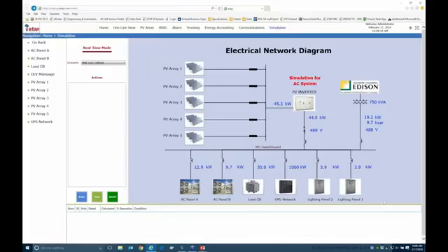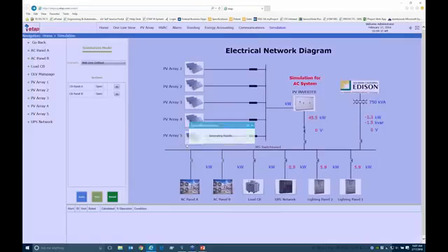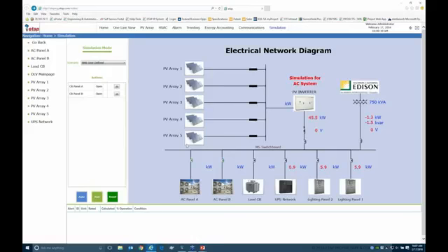And what if I just wanted a quick control decision to be made? Well, what if I shut down all the air conditioners in the building right now? So I can double click on those two breakers. You'll notice that I originally had them in black, and I'm going to go ahead and open them so it'll turn green. So I'm opening these two breakers, and I'm going to press run. Now I'm actually running a simulation inside ETAP and bringing those results back into my dashboard.